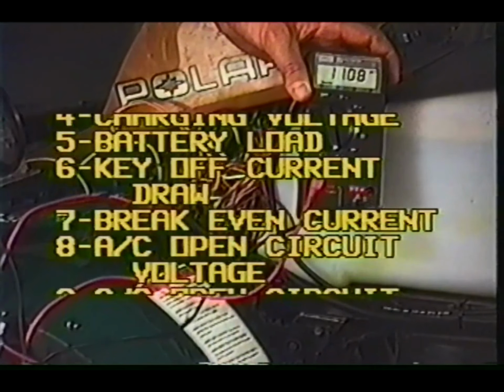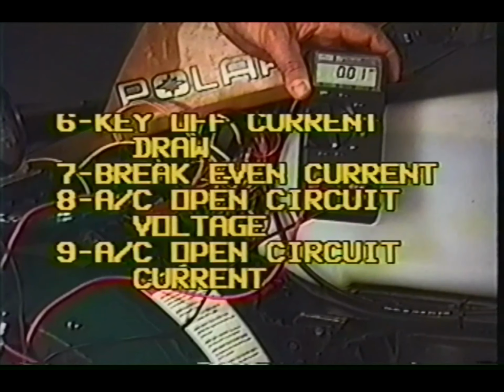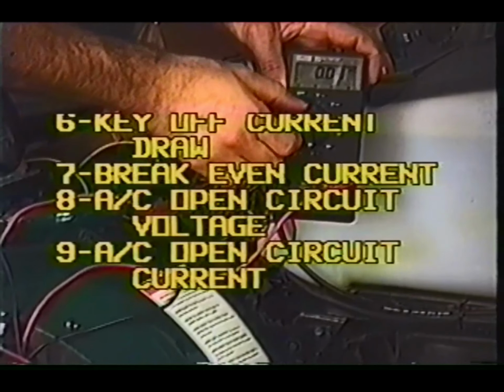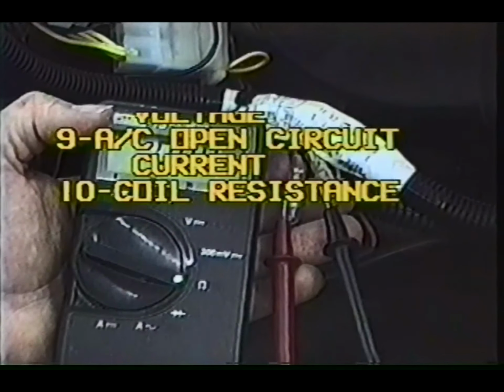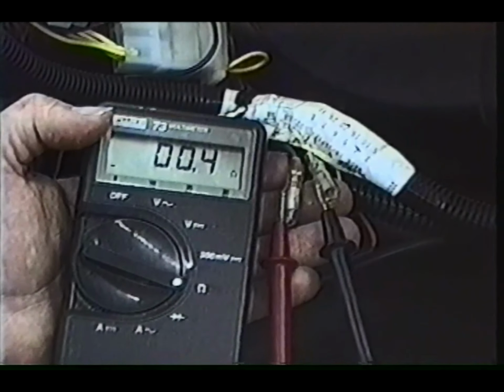Alternator output can be tested by isolating the stator coil wires from the rest of the system and performing the AC open circuit voltage test, as well as the AC open circuit current test. Use an ohm meter to check the condition of the charging coils and compare these readings to the specifications listed in the Master Repair Manual. Once you have found and repaired the problem, don't forget to go back and verify system operation. We hope this time spent in electrical theory